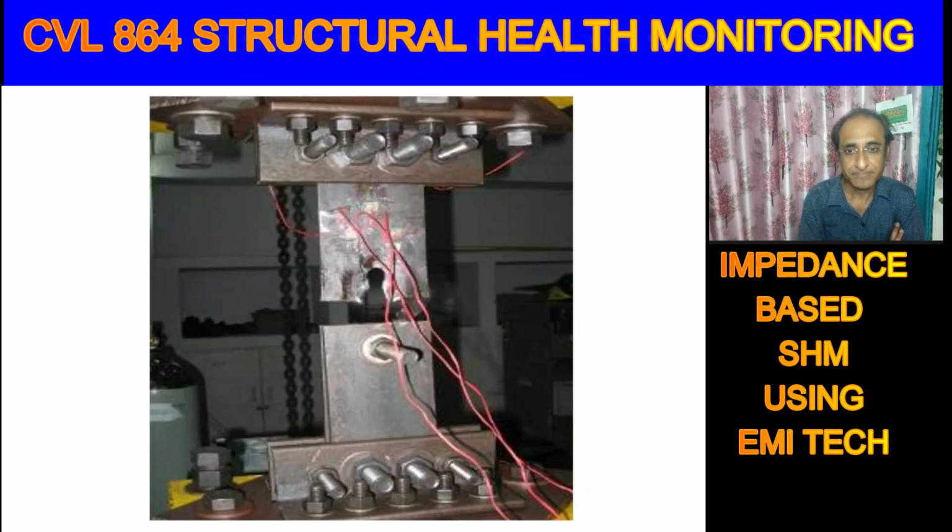Is it tensile failure? Is it bearing failure? The other type of failure is tearing failure. So it could be tensile failure or bearing failure. This is bearing failure. This is not tensile failure. Tensile failure means that the section breaks from here. That will be the tensile failure. This is a bearing failure. So the bolt has basically failed the plate in bearing.